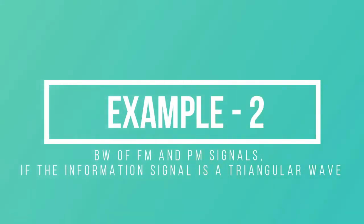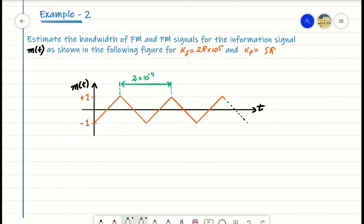Example number 2. In this example, we are required to estimate the bandwidth of frequency and phase modulated signals for the case when information signal is represented by this triangular signal, that is m of t, where the scaling factors for the case of frequency modulation and phase modulation are given as kf and kp.